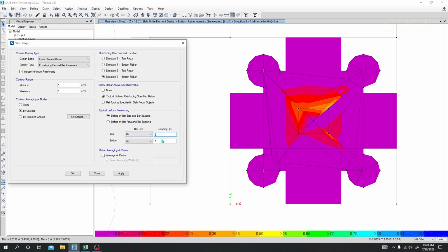So as this is for bottom, I'll change the bottom reinforcement to 4 inch center to center spacing. So this is also okay, and if I just go for number 7 bar, then it also can be okay. Here we need a little bit of reinforcement, so we can neglect that. In this way, for every portion, I mean for every direction, you have to design and go for the final process. So this is the total procedure to design a pile cap perfectly.